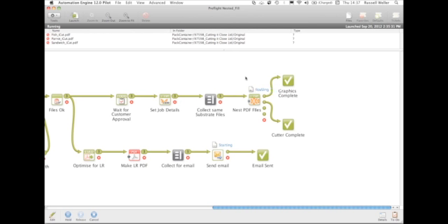Again, if we just watch that to see the speed. So this is taking an 8x4, 1220 by 2440 sheet. It's nesting those 3 files for me. It's doing a duplex, so it's doing a front and a back, and it's creating all of the relevant cut files from that as it's doing it. Again, in the meantime, obviously that's sending an email for me as well.